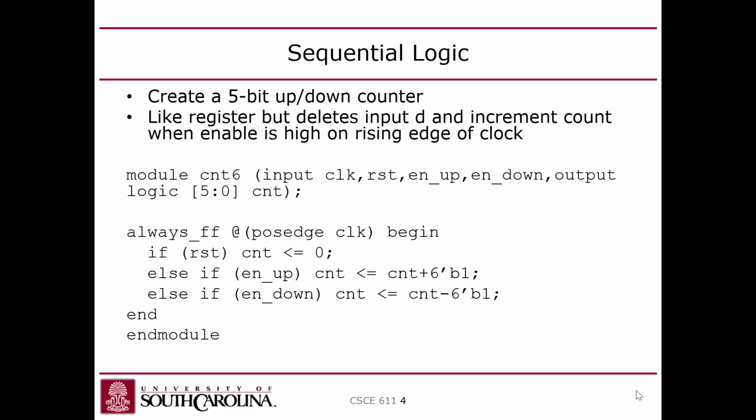But that's not it, because you also had to keep track of which way you were shifting it. So you had like 26 positions where the LED could be located at any one time, and then there was also this notion of, am I going to the left or am I going to the right? So there's like 52 states that the system could be in. Make sense?